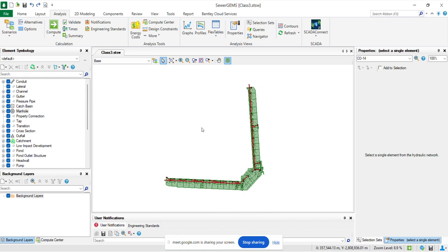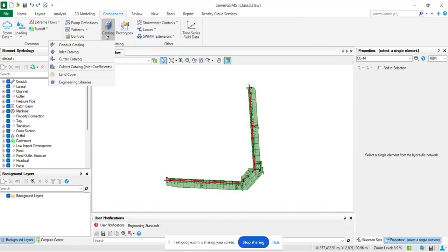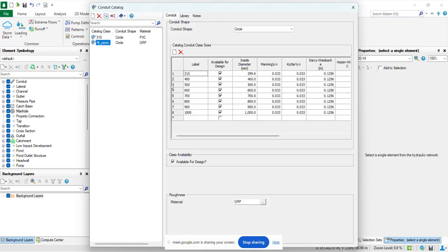If you are giving a steep slope for the bigger pipes, it is not an efficient design. I will show this. Go to conduit. We are going to use this many pipes in this area. Based on the flow, it will automatically choose the pipe size. If you are not specifically mentioning the slope, like for the 315 it should be 300 to 400, it will automatically take like 500, 600, something huge. So for the smaller pipes we can go for steep slope.